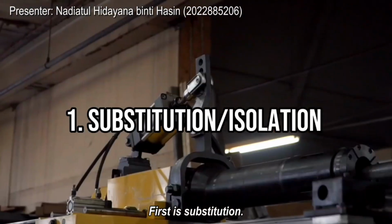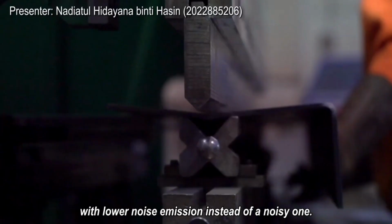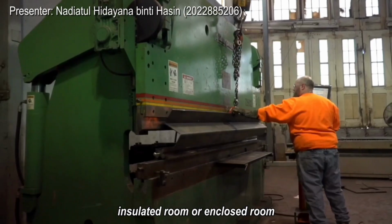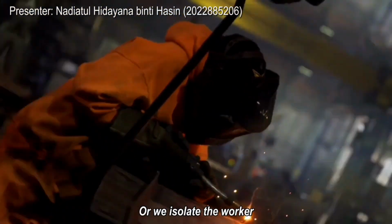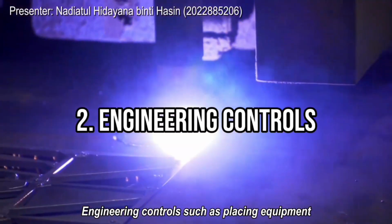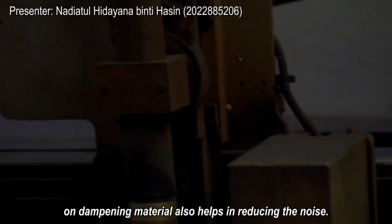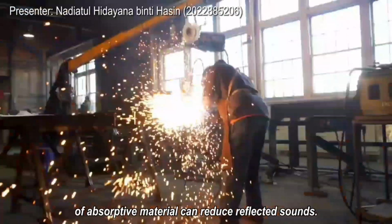First is substitution. By using equipment with lower noise emission instead of a noisy one, isolating the noise source in an isolated room or enclosed room also helps in reducing the noise emission. Or we isolate the worker from the noise source by placing them in an enclosed operating location. Engineering controls such as placing equipment on dampening material also help in reducing the noise. Using a noise reduced saw blade or barrier made of absorptive material can reduce reflected sound.